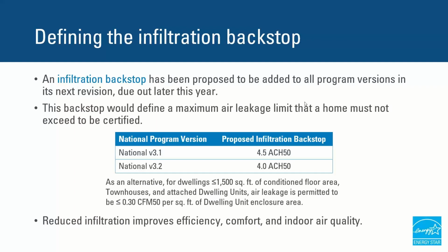But we still have prescriptively required for all dwelling units a 0.3 CFM compartmentalization metric as part of our RADAR field checklist, and that still holds. So for the reference design for version 1.3, we're proposing 0.27 is what you're benchmarked against, and we still have our 0.3 infiltration backstop required for all dwelling units regardless.